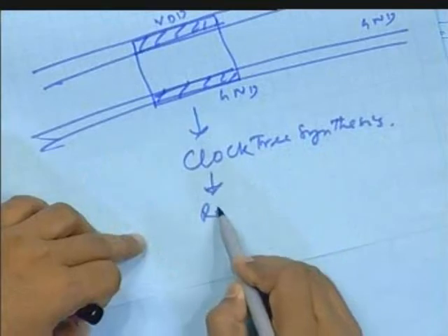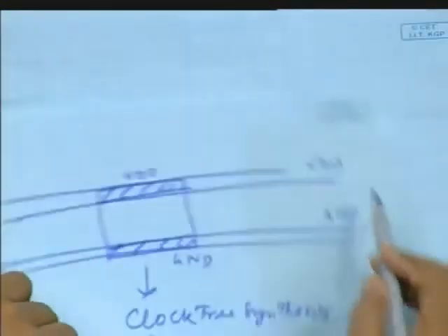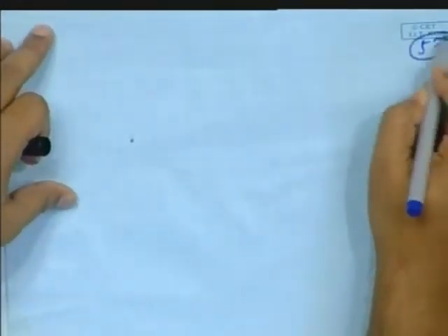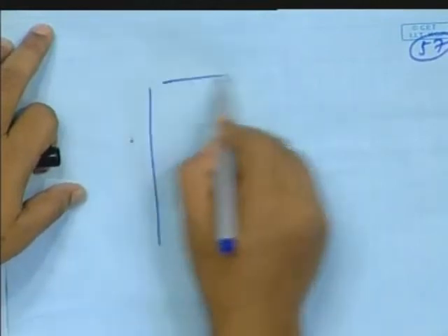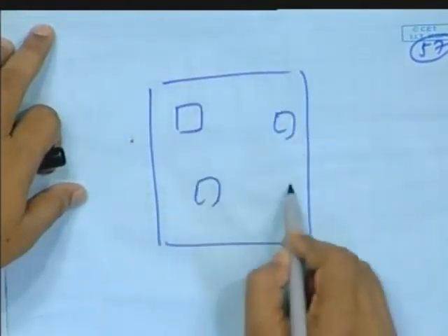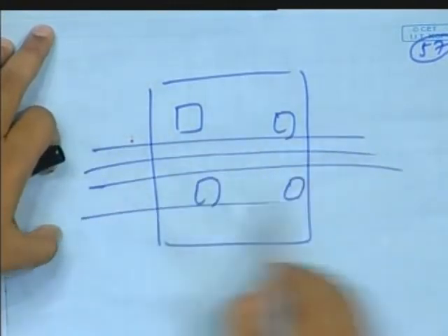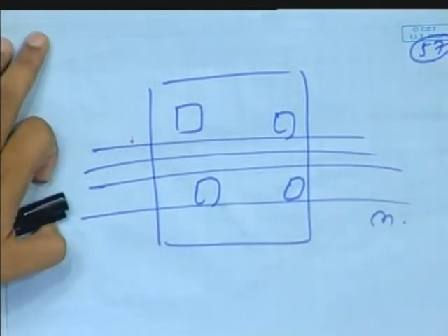Okay. Congestion map means what? Congestion map means, okay, after this you have to go for routing. Every time what you have to do is, say, this is my chip. If I do a virtual placement like this, I have to have these many horizontal connections, n number of horizontal connections.